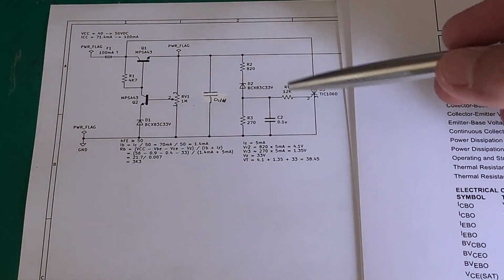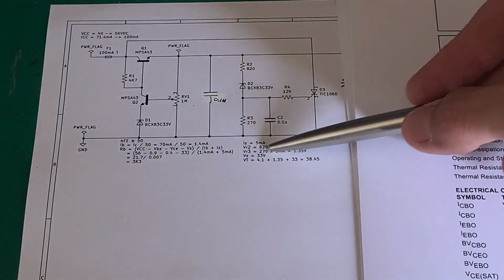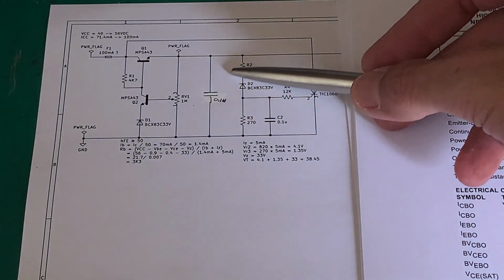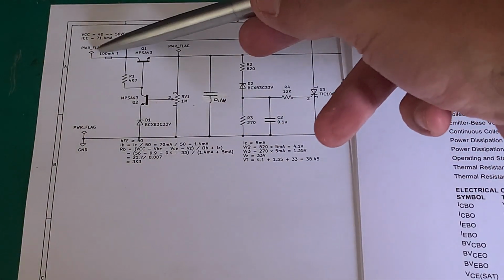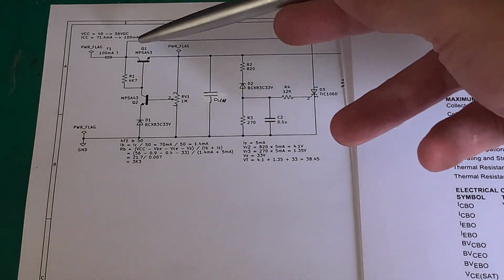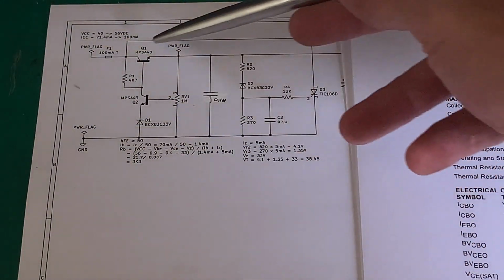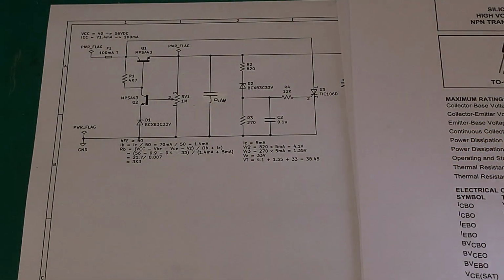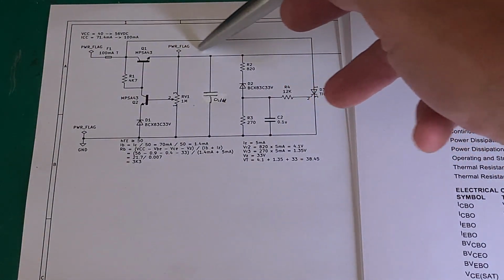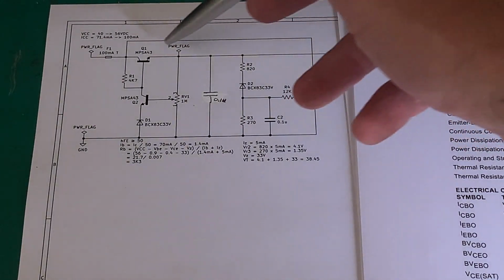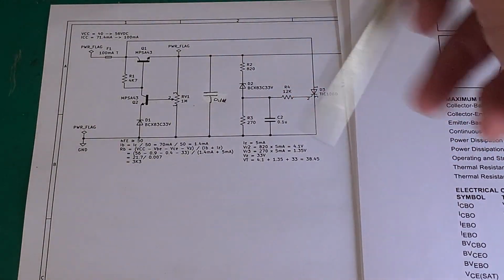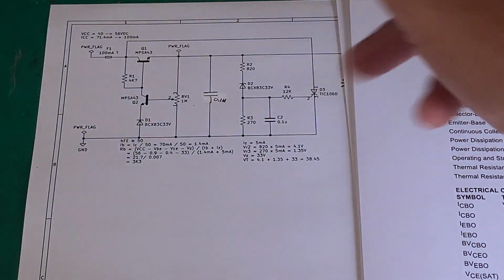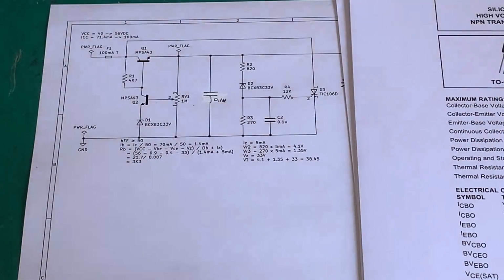now today we're going to talk about a crowbar, which is this circuit here. So you'll notice I've got a fuse here, and you'll notice in this calculation we calculated this base resistor based on the voltage and current we want out here. So this transistor in effect is going to limit the current.